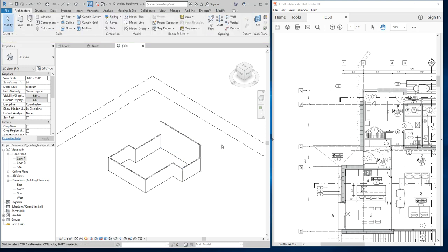Okay, yes we can. So this is an AutoCAD command that we learned. It's match properties. Everybody's like, oh yeah, Revit has match properties. It's essentially a matching tool, if you haven't used AutoCAD, where I can touch an object that I like the definition of, and with my cursor I can capture all of those settings, and then I can apply them identically to another item, right?